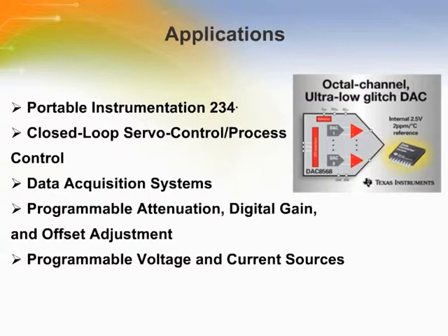These devices, targeting applications such as industrial process control and portable instrumentation, the DAC 8568 16-bit, the DAC 8168 14-bit, and the DAC 7568 12-bit digital-to-analog converters from TI, integrate 8 channels in a TSSOP-14 package or TSSOP-16 package.